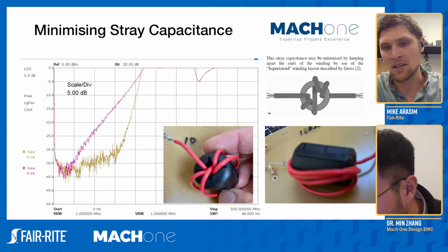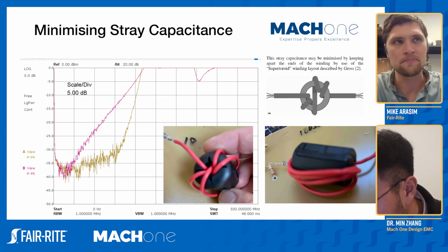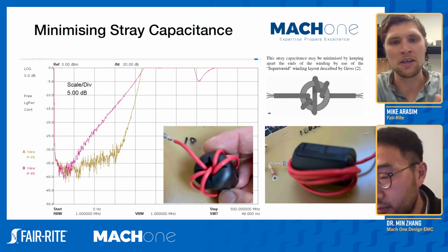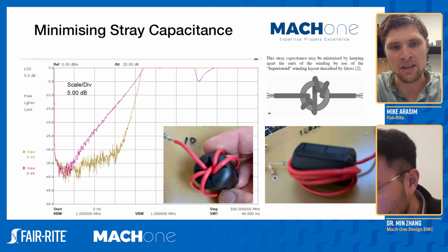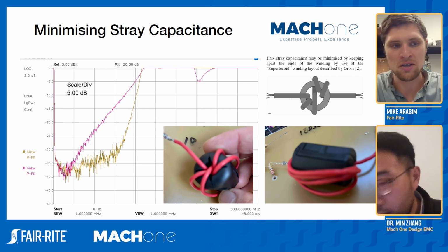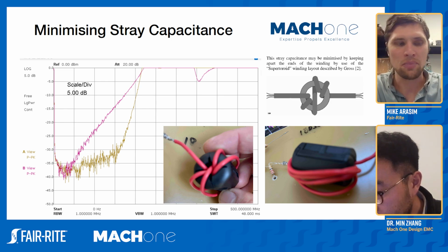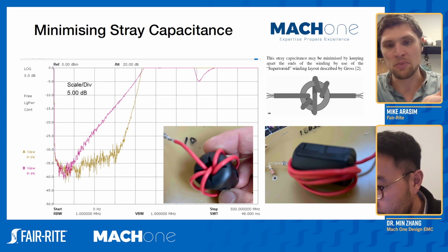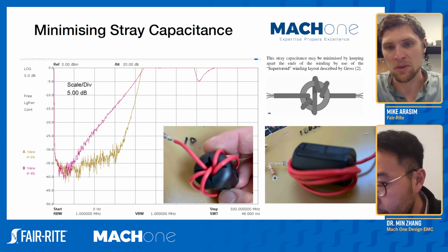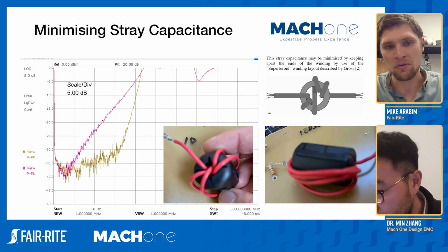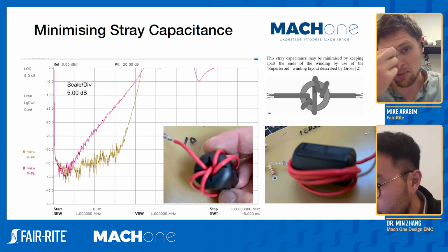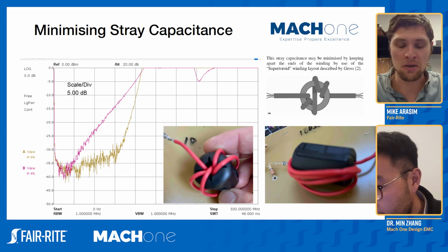But once we start getting into, depending on the core size, 3, 5 more turns than that, you're going to see that same increase in impedance at low frequency, but around your peak impedance, which, by the way, the frequency of that peak impedance is going to be shifting lower and lower in frequency, you're going to notice the impedance curve gets very peaky.